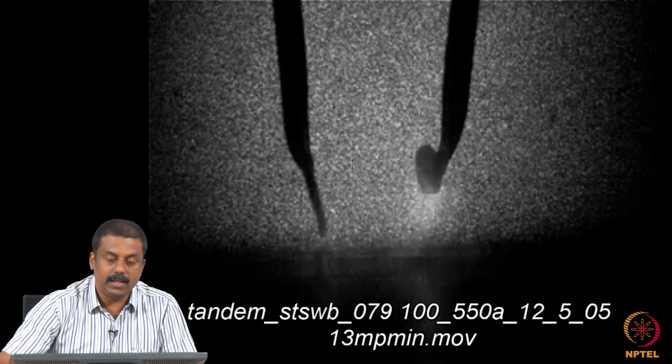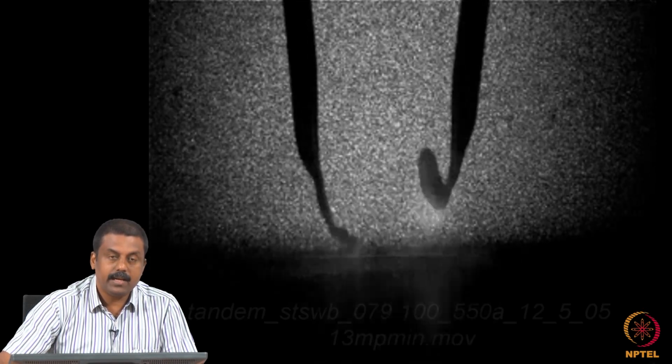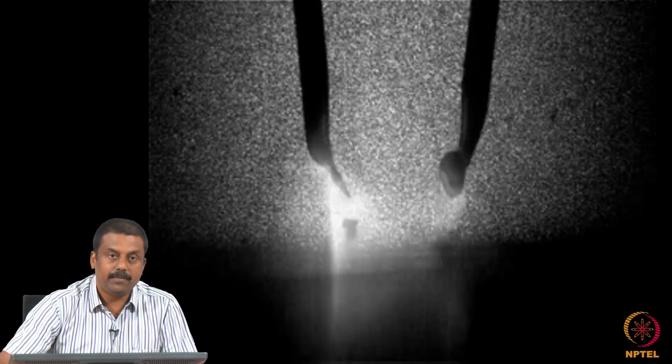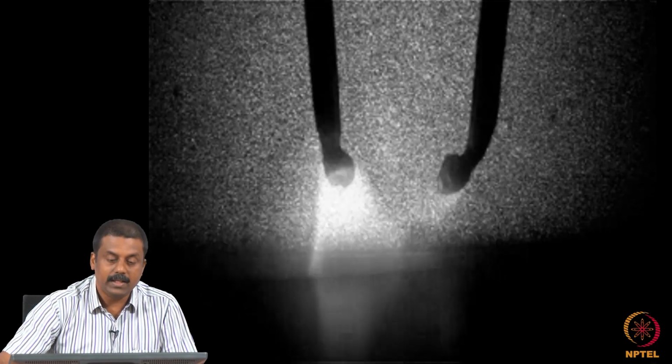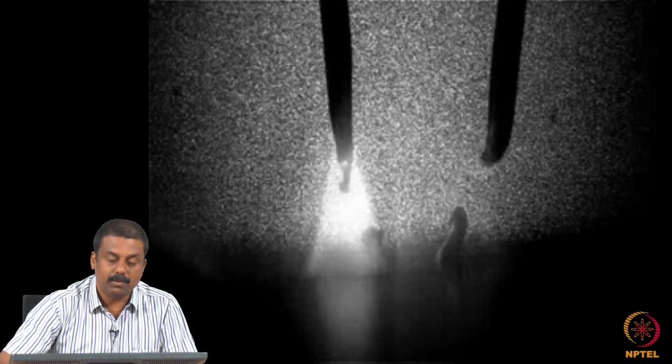So the important characteristics of this process are controlled by the current, the amperage we send, the shielding gas we use, as well as the melting characteristic of the electrode, which is also controlled by the current, as well as the diameter and the stick out length, the distance between the contact tip and the workpiece.